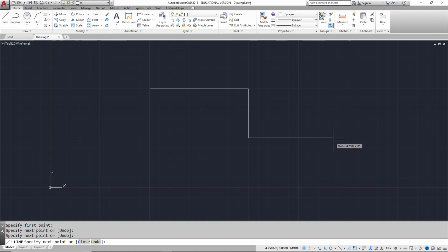But if I wanted to get exactly at 5 inches, it's very difficult with using just the grid to get exactly to 5 inches. Notice that I'm at 4.9905, but then if I move my mouse a little more, you see that it jumps right over to 5.0023. It's very difficult to get exactly to an exact number using just the grid. So for that reason, we have instead what we call snap.